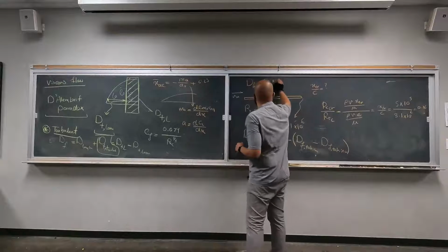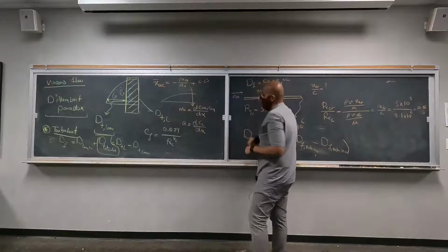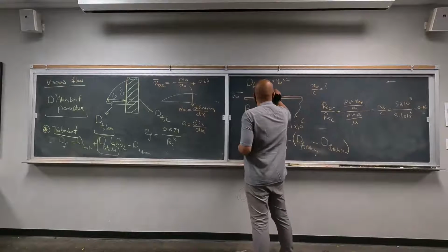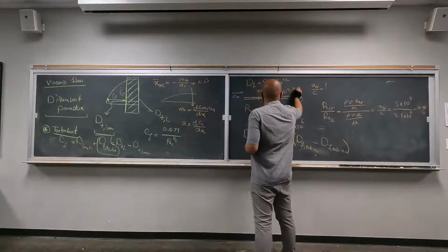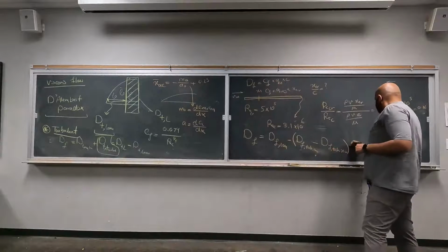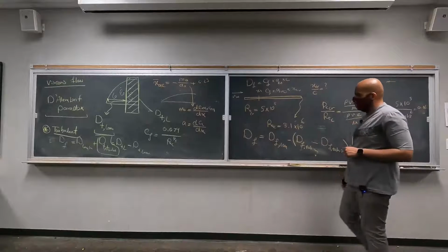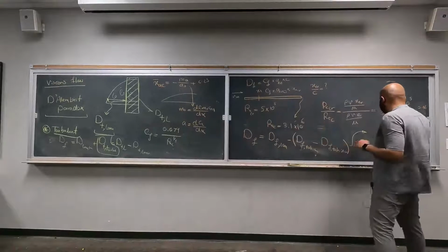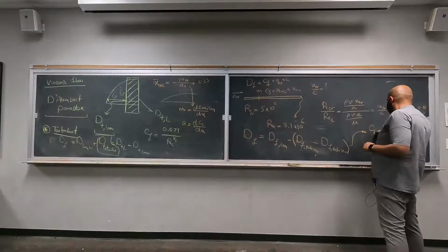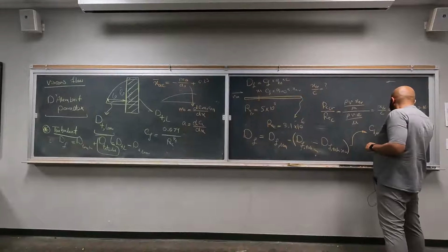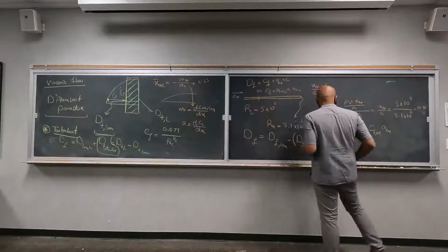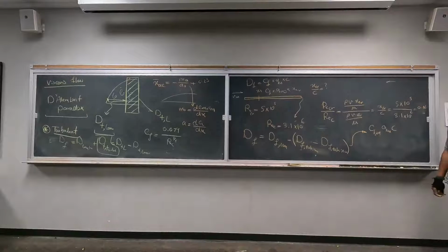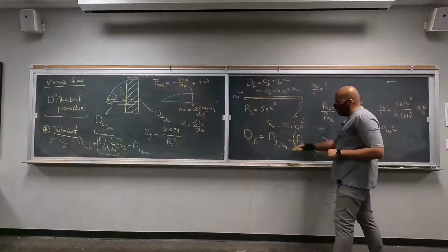CF multiplied by Q infinity multiplied by your chord length or x critical, depending on the length, right? Okay. So this dF is your net CF, right? Net friction coefficient. This is something that we want to find. So CF, I'm going to call it CF net, Q infinity, and this is true for the whole plate, multiplied by C, right? Is this clear?